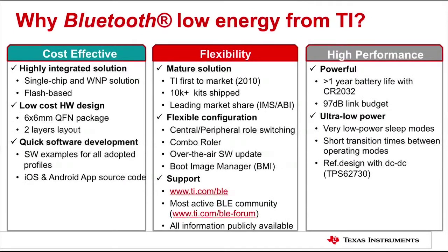So why TI Bluetooth Low Energy? I think the key things, very similar to the Bluetooth solutions, are your cost effectiveness, your flexibility, and your high performance. So from a cost effectiveness, you're really looking at a highly integrated solution. So we talked about it, that it's an SoC, it's flash-based, makes it low cost. The package itself, it's a small QFN package. The reference design that goes along with it is 2 layers, which makes it lower cost for you. And then quick software development. So you've got a lot of software examples out there. You have the source code for the different apps on the iOS and Android.